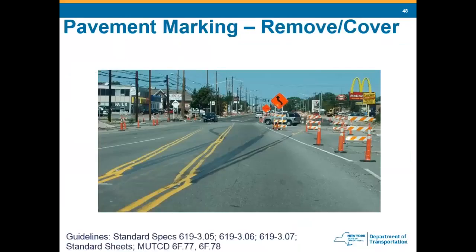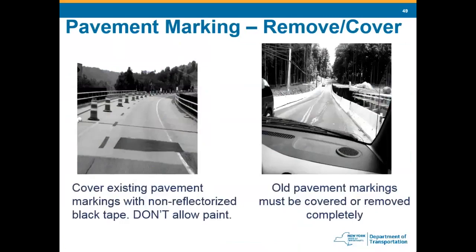Pavement markings that are changed need to be covered well. Not the best. Not the worst I've seen, but it's definitely not the best. Should be covered completely. This one's pretty good. Non-reflectorized black tape. Shouldn't allow paint. This one, they don't like it. Bad weather, nighttime. Somebody could get confused there.